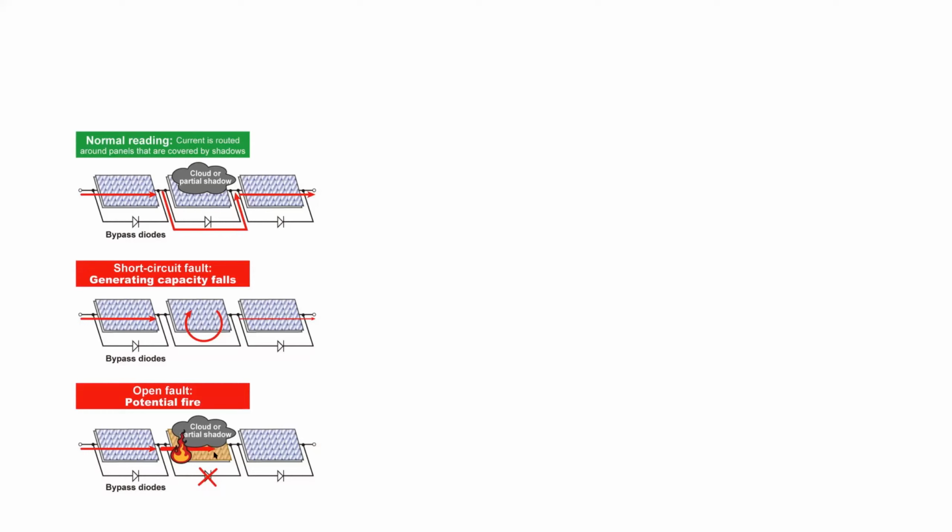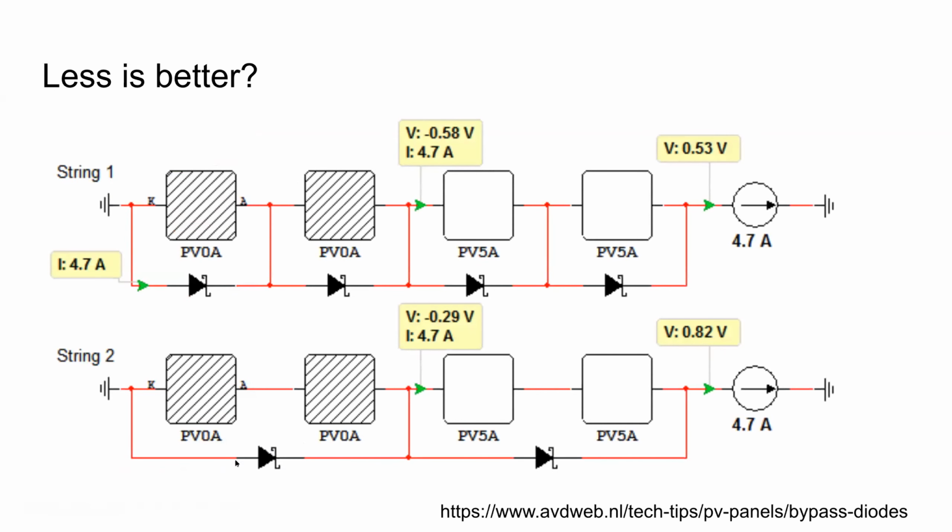For example, if you don't have a diode, you try to run the array at the current that's optimum for the non-shaded arrays. What could happen is that you get a negative voltage over the array and you force current through it, which basically means you dissipate some power from the non-shaded arrays in the shaded array, and it can get really hot and damage the array even if you do a bad job in regulating this. So that's why you have diodes.